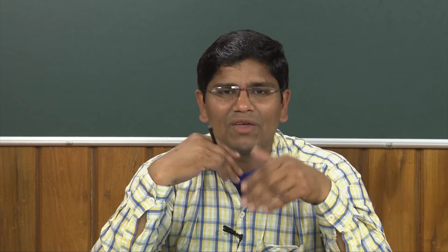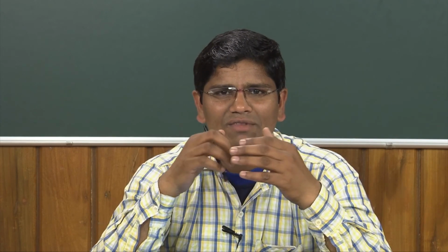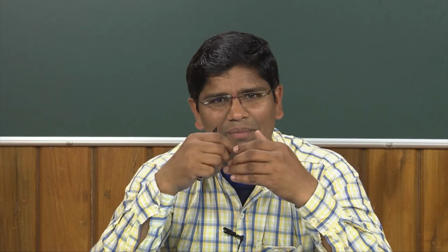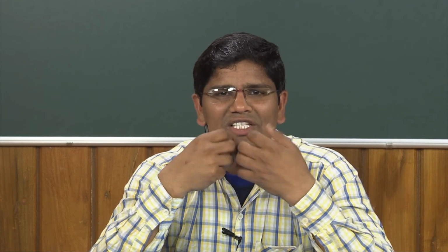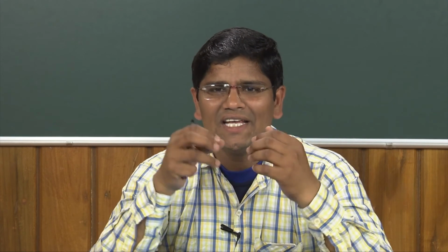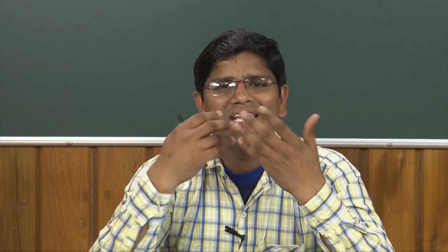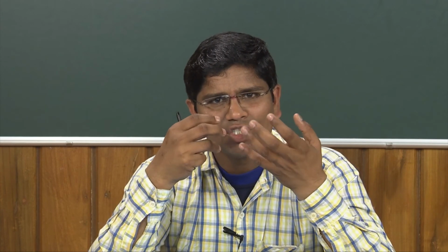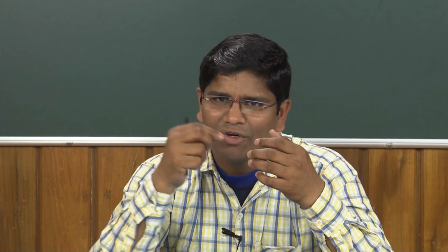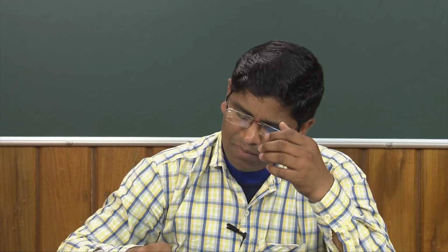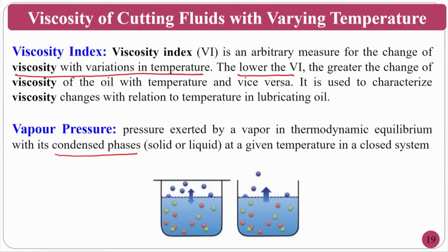At the same time, the viscosity index I am talking about, if the viscosity index is lower, what will happen? The viscosity will change. If it changes easily, this capillary action will be very easy. If the viscosity is low, what will happen? The cutting fluid can penetrate into the complex regions of the machining region. That is why vapor pressure has to be exerted, and the viscosity index should be lower.